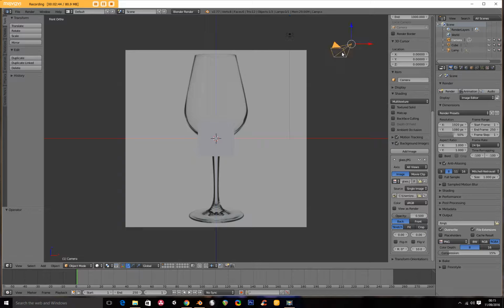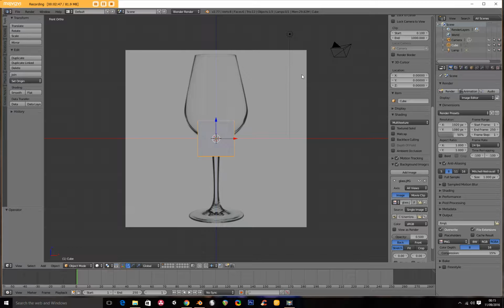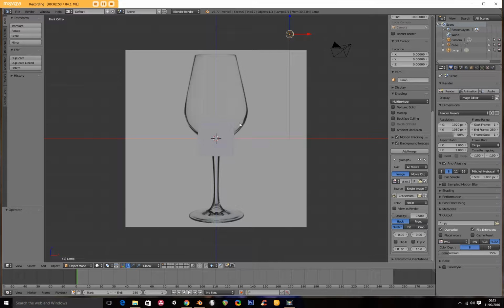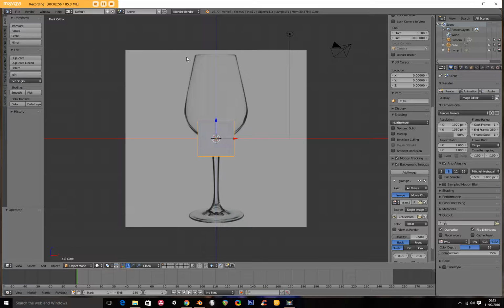So in Blender you can select all the various objects that are in the 3D viewport. At the moment we have 3 objects. If I had 10 cubes I could select each one individually, and then if I wanted to change the shape or size of one of them I would change mode. So here it says object mode, where we have individual objects that we're manipulating, and then we can go to edit mode, and edit mode is to change the shape of any one object. It doesn't work on lights or cameras, you can't edit them, but on the meshes that we'll use to make all of our game assets we can go into edit mode.